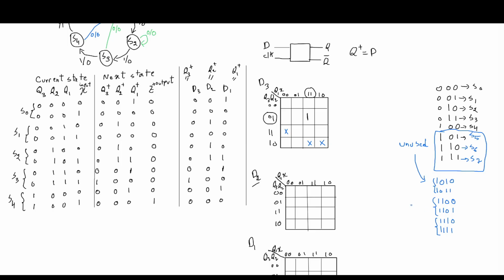Next, we have 1 1 0 1 in this location, don't care. Last one, we have 1 1 1 0, this is don't care. And then lastly, 1 1 1 1 in this location. Now the rest will be zeros. It is very important to know where we have don't cares because this will give us the absolute minimal Boolean expression form. So now we can group this one with this don't care term and treat this don't care term as 1.